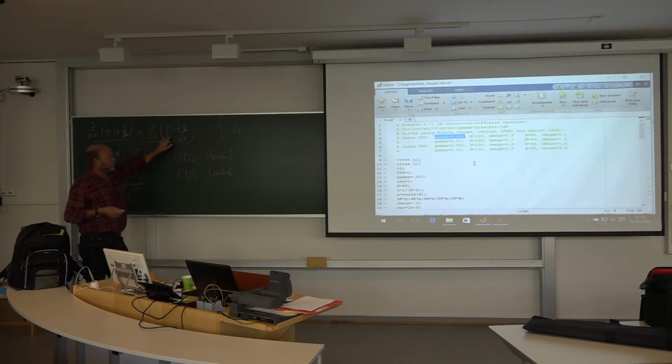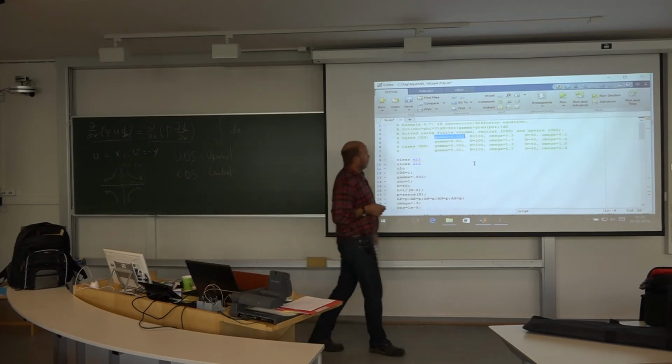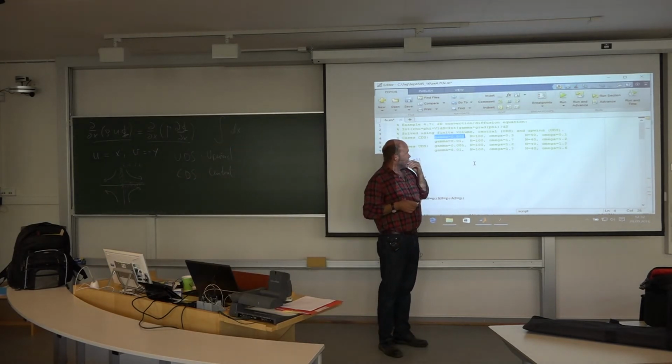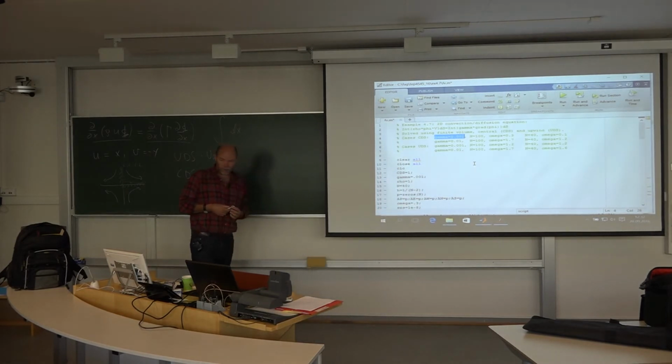So the smaller it is, the more in trouble we will be when it comes to stability. If it's a very big one, it's a very sticky fluid, like honey or something, very stable, no problem. So we start with it fairly small, 1/1000.